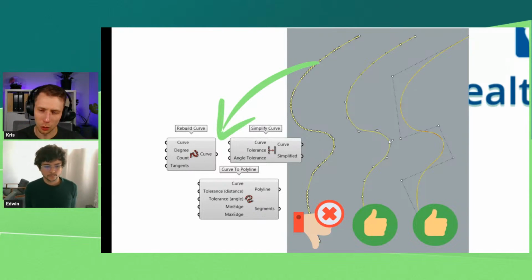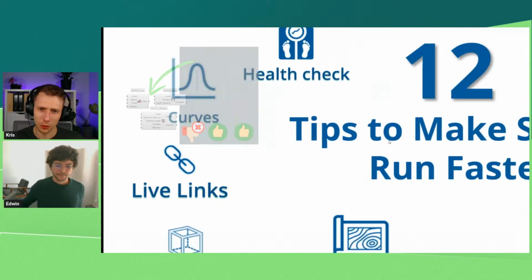So second tip: always when you are importing some geometry into Rhino, try to transform this geometry into Rhino geometry, so it will be natively created geometry through Rhino. And if later, in more advanced scripts, you are working with Python scripts or advanced plugins, it will help you a lot, because if you are using native NURBS curves, you will have much easier work to do and you can avoid lots of problems. Okay, so that was the second one.